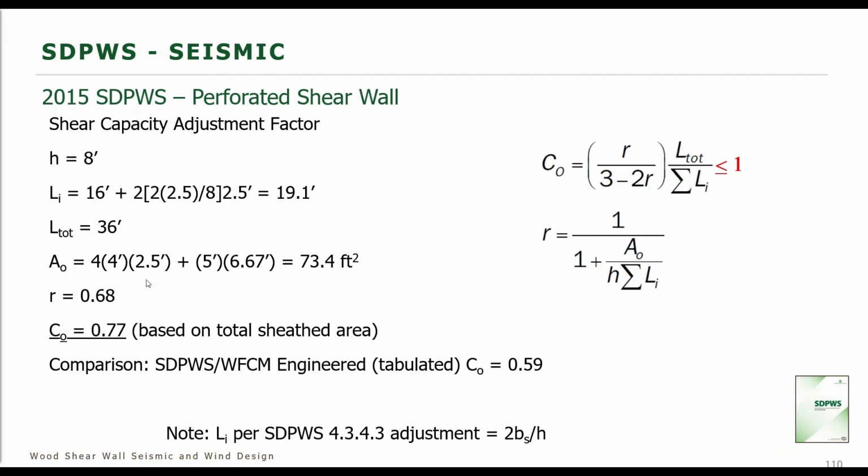Okay, so here Lori went into detail by fine-tuning her design in the perforated shear wall approach, where instead of taking the largest opening, we are now finding the shear capacity adjustment factor based on all the sizes of the openings, and finding efficiencies there.